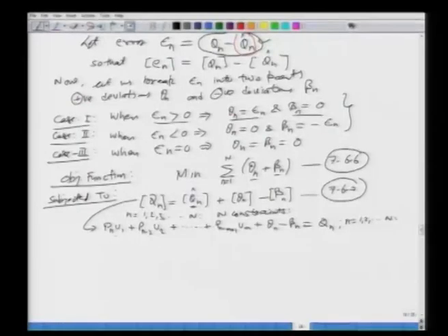The second constraint we impose is that this unit hydrograph ordinates which we find should be such that the area under the unit hydrograph should be equivalent to 1 centimeter of effective rainfall, or the direct runoff depth should be equal to what, unity, all right. So, we ensure that, and the next constraint then we say is that the summation of u m's should be equal to k.